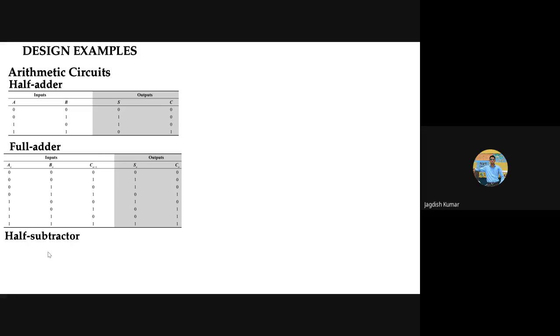Okay. Next thing, we may come across the operation of subtraction with the help of digital or binary circuits. So the binary subtractor, similarly, there is a half subtractor. If you subtract 0 from 0, output is going to be 0. There is no carry. Rather than carry, we should say borrow, B, or you can say C for the borrow bit, because B is already used here. So that's why they have written C here. It's not carry, I mean, it's borrow taken from the higher significant bit.